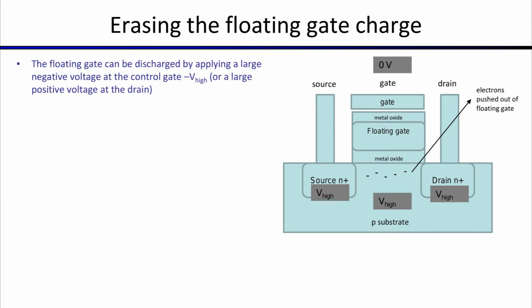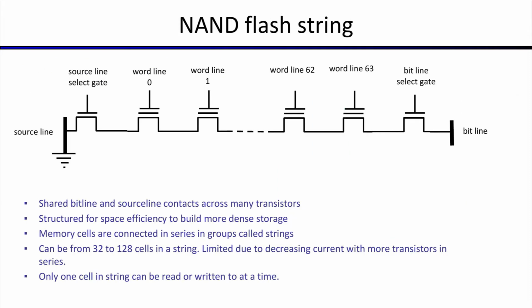Now, without erase cycles, you can store the charge in the floating gate for over 10 years, 20 years. It's a long enough time frame. But only the number of program and erase cycles is limited. So that is a caveat that comes with these devices. Now we get from a floating gate MOS transistor to how it is used in flash storage.